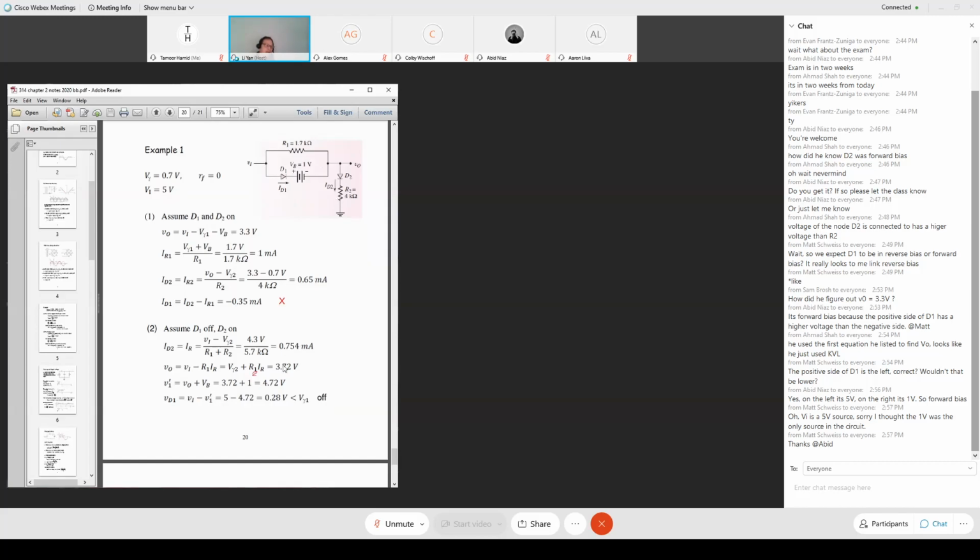Okay, once you calculate this current, I want to find out what's the output voltage. How do you find the output voltage, VO? Here I have two expressions, two formulas. I can calculate it in one of two ways, either way. Output voltage equals input voltage minus the voltage drop across resistor R1. So it's VI minus R1 times current IR.